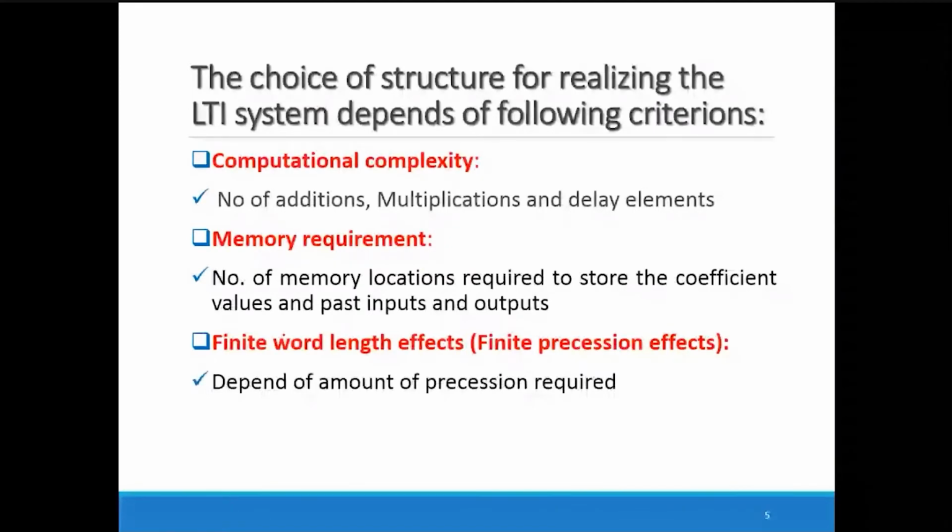First one is the computational complexity, as we have calculated in DFT and FFT. Here the same thing we apply, but one more thing is added. Number of additions, number of multiplications, and delay elements. These three parameters we have to calculate and compare to decide which structure to select, based on the number of additions, number of multiplications, and number of delay elements required.